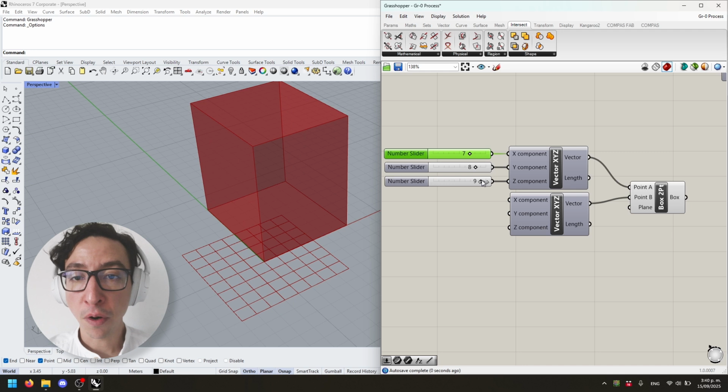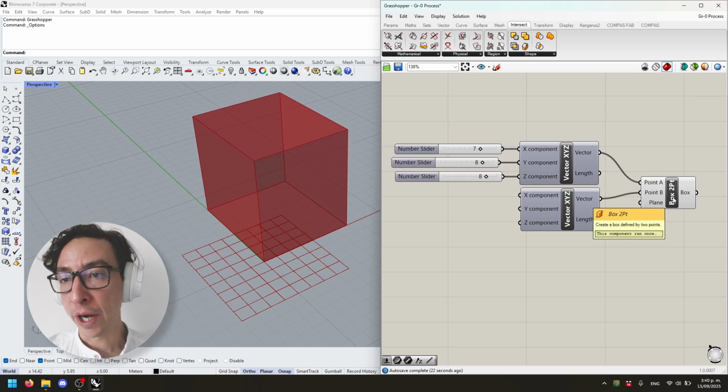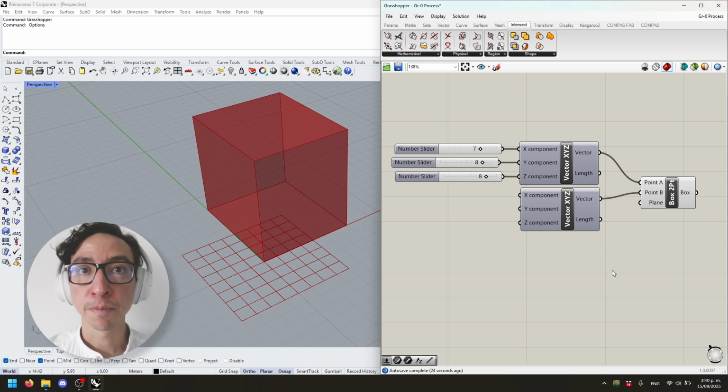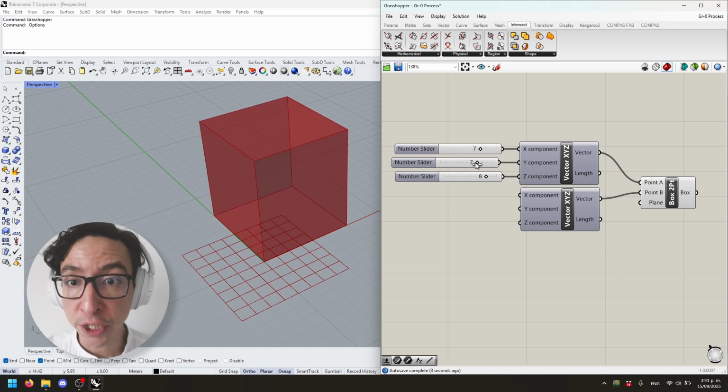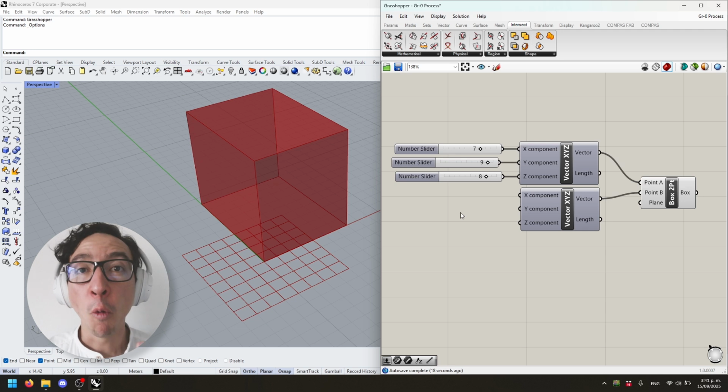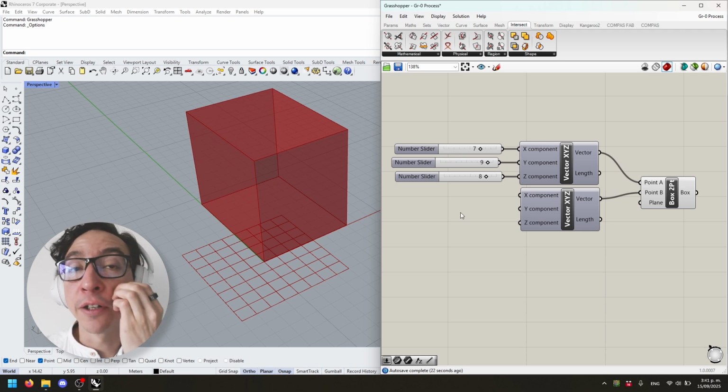And you can modify as you please. Now we're going to export our STL. You need to bake the box. What is bake? Understand that in Grasshopper, the elements created are just virtual, the result of a process that can change at any moment. When you bake them, they are no longer parametric, they are just physical results.